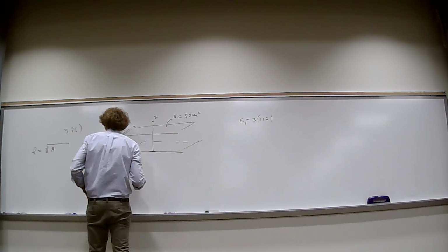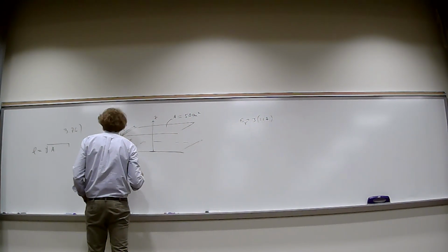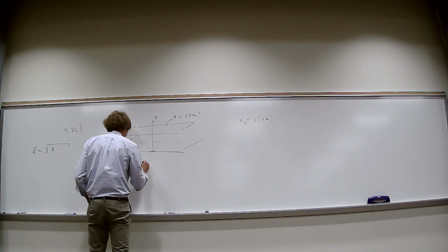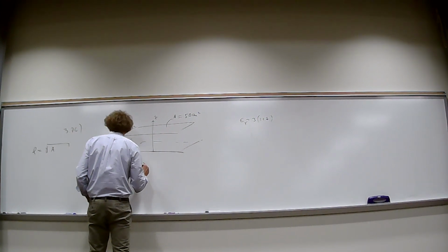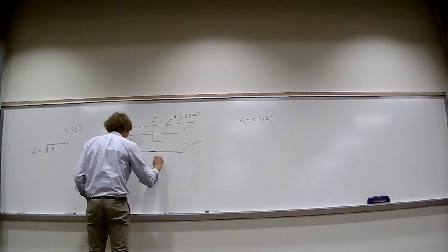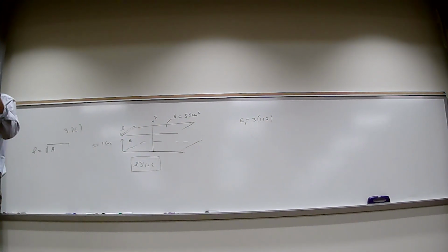And actually, the value I'm going to give you should be even larger, but normally what they say is L, right here, has to be greater than, usually a lot greater than S, but usually L has to be greater than 10S. Now, that's if you want to ignore fringing. What I'm really saying is that's a very thin structure. If you look at the length of one of those edges on that plate, that edge will be at least 10 times the spacing between the two plates.